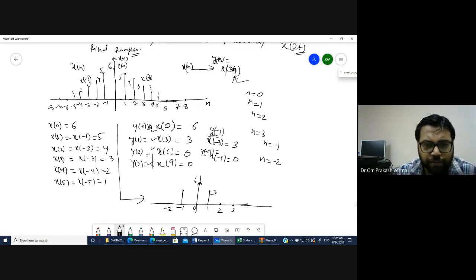When you multiply the signal with 3, n, when alpha or 3 is there, it means you have decimated, you have eliminated 2 signals in between the first 0, 1, 2, 3. So you have eliminated 2 signals in between in 3n. If we are taking 5, then you have to eliminate 4 between them. From 0 to 5 you have to eliminate 4 signals.